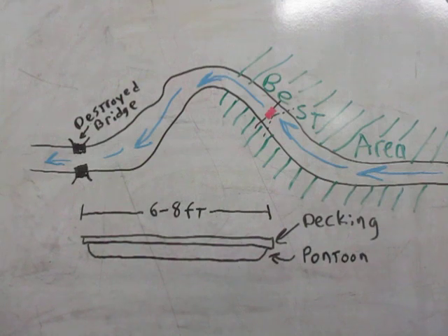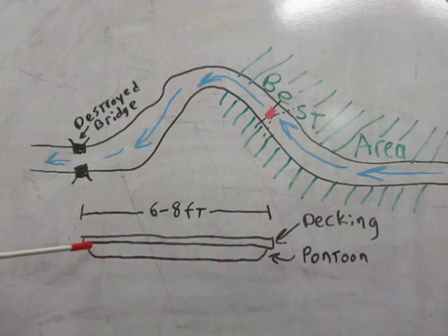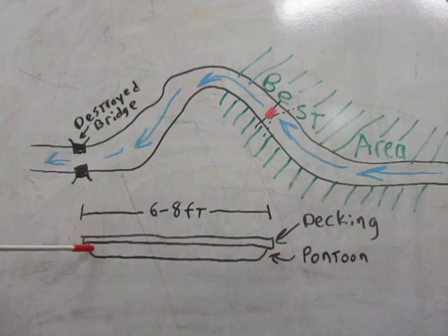Another thing would be taking some logs, kind of rounding the bottom edge behind your cut, so that way when it starts to beach itself, it's going to ride up onto the beach easier, or if you come across any type of rocks or obstacle underneath, it'll kind of get fed underneath the pontoon, hopefully without stopping it, depending on how low it's riding in the water and how much of an edge you put on here, if it's rounded or if you just kind of straight cut it at an angle going across to make essentially a ramp.